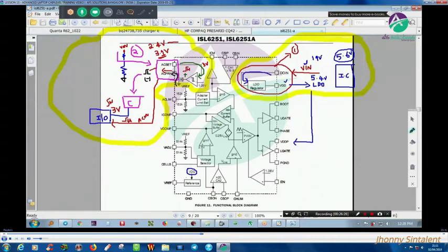So this will release a reference voltage confirmation, and this reference voltage confirmation will be 2 volts. If this confirmation is not released, that means there is a problem here or there is a problem in this low drop output. So this is my point number 3.